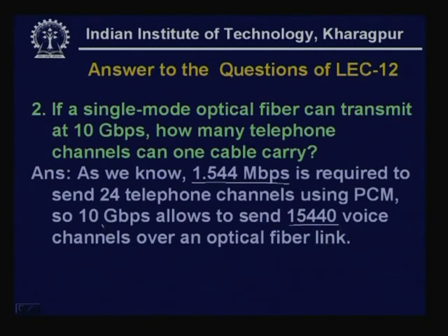You can do the calculation; considering 24 channels per 1.544 megabits, you will be able to send 15,440 voice channels through a 10 gigabits per second channel in an optical fiber. So, you can see a large number of voice signals can be sent through a single optical fiber.